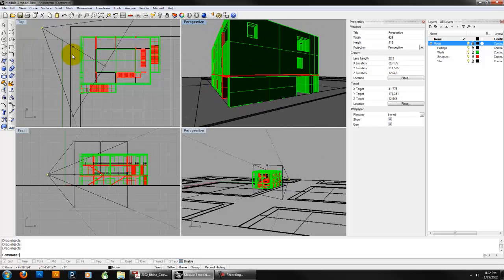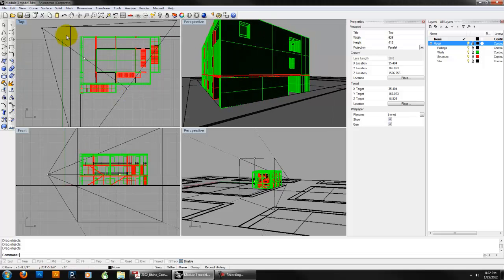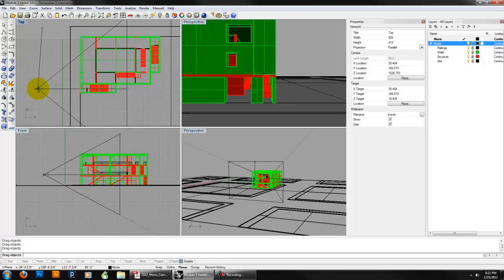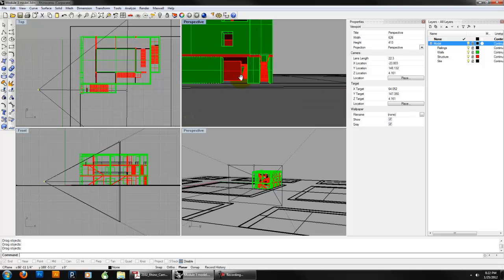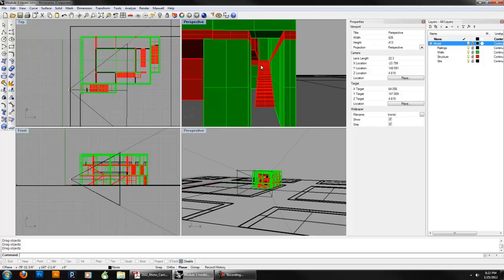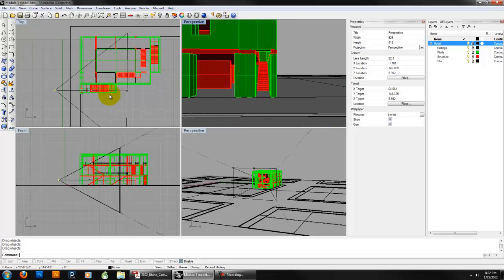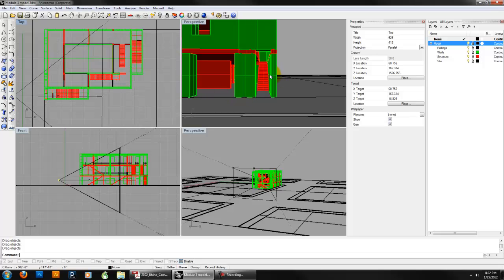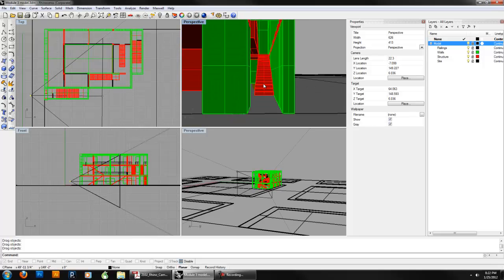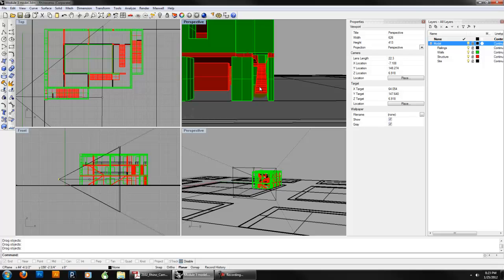And so, I can view down this corner. What if I wanted to view down the other one? I could pick my camera point and then move this camera point this way, and so now I'm viewing down this hallway. And again, panning is useful because it doesn't affect that. And if I zoom, I can actually see what zoom's doing. Actually, in the camera, zoom is moving the camera point in and out. Okay, and it's changing the field of view here. One way to move the entire camera without moving it in the viewport by panning is to use the armature point, which is the center point.